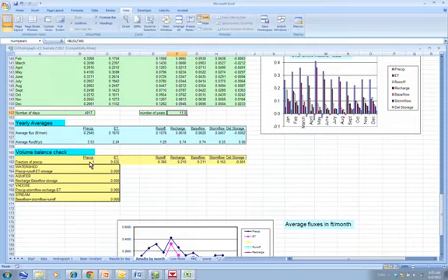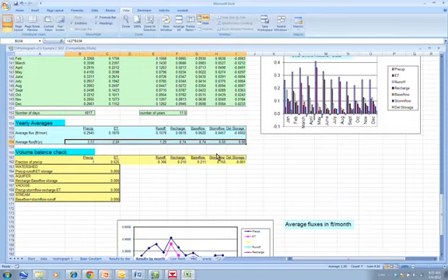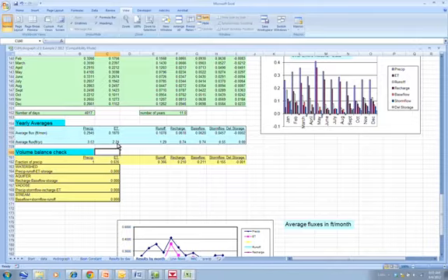What's shown up here is to take these different values of flux and normalize them to the precipitation. So if you took that number and just divided by that number, you get ET. And here, ET is 63% of precipitation, so we recognize that as a pretty typical value. And runoff is a little bit higher than recharge. Base flow and recharge are pretty similar.